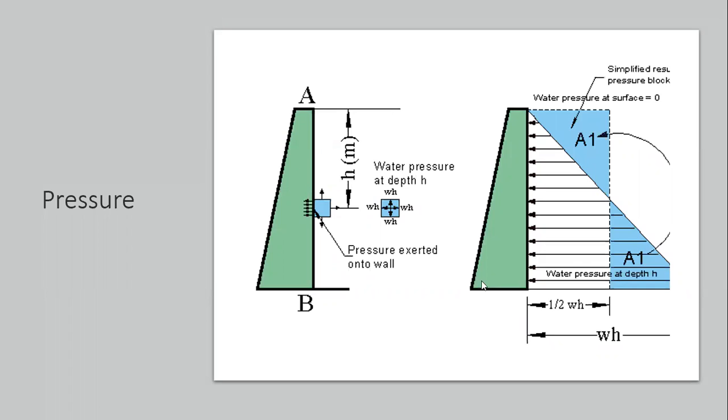Of course, pressure works the same way as a force, but the only difference between a force and a pressure here is that the pressure is used in a way that simulates the behavior of fluids or gases, either inside of a tank, which is fully sealed, or a tank that's open to the air, such as water pressure. And the only difference between force and pressure here is that pressure could be expressed in functions.